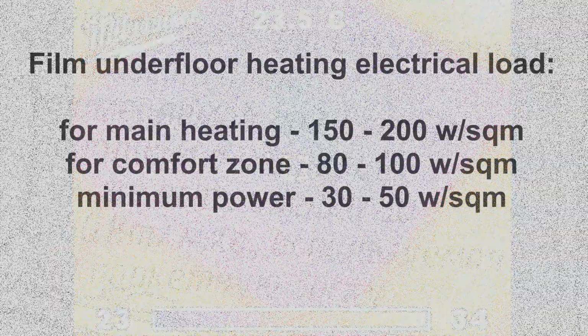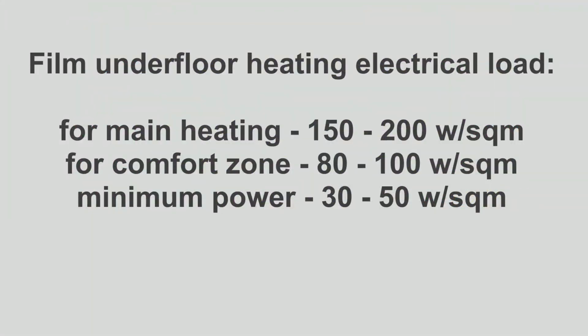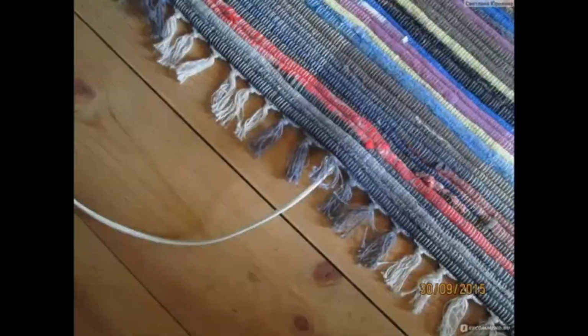When you want to heat the whole house with this type of underfloor heating you must have the necessary electrical power. For an apartment, such power may be 7 to 10 kilowatts of peak load. Also, a small advantage is that such a warm floor can easily be made mobile. If we stick an infrared mat on a carpet and leave a wire from it, we can make portable floor heating, or by the same principle make a heated blanket.